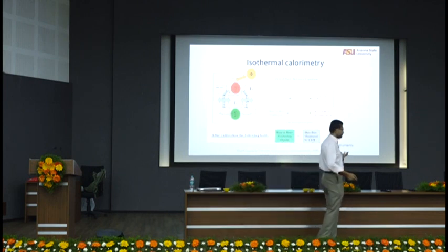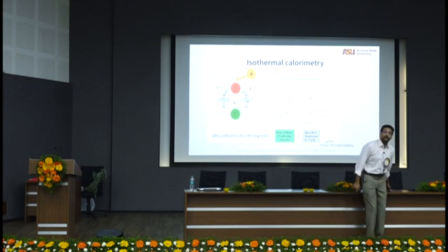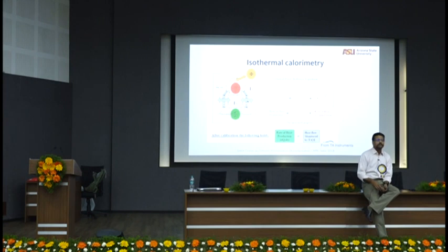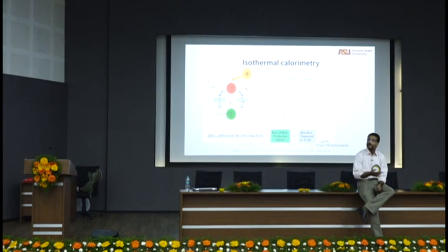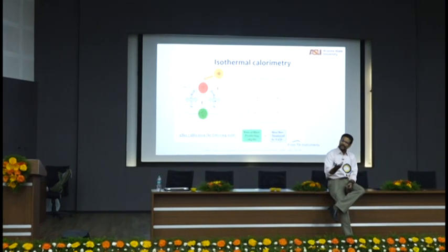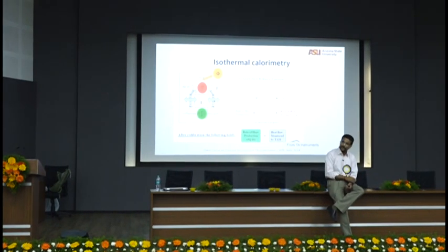So heat of hydration is a good way to tell you how much of the cement has reacted, and finally you convert it into a term called degree of hydration. You use degree of hydration, which is effectively a parameter derived from heat of hydration, to tell you how much of the cement is hydrated. Now, this again is an important determinant of the microstructure.